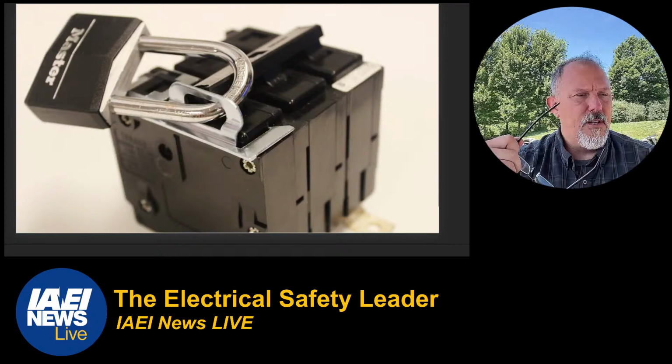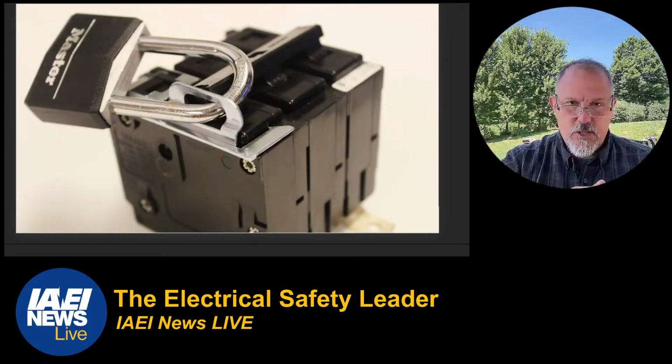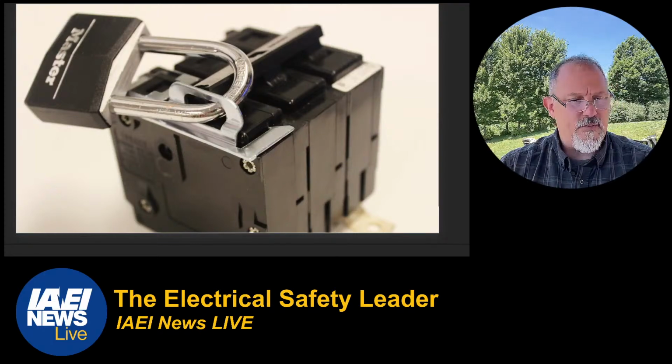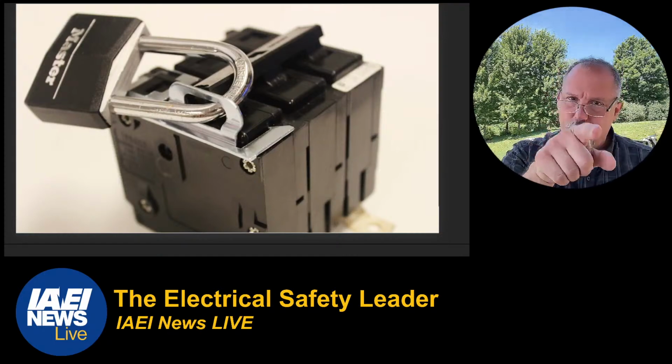If you are talking arc flash PPE category, then you're going to look at the enclosure. If you're using the table method, you're going to do 130.7(C)(15)(A), and you're going to follow those procedures. So, Mr. Snyder, I'm not sure what risk category you mean. Give me a reference when you talk about a risk category 1. Help me understand the category. What section are you talking about with regard to a risk category? I would love to answer that question, but I need more information from you.